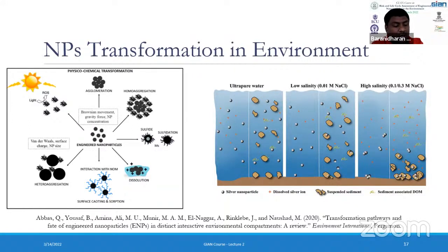So natural organic matter, which is present in natural streams of water, mainly surface water, refers to the heterogeneous pool of organic compounds, ranging from macromolecules, be it humic acid or fulvic acid, or otherwise extracellular polymeric substances, to low molecular weight substances such as carbon-based compounds and ligands, mainly chlorides or sulfates based amines, carboxylic compounds, OH compounds, and thiols, that is nothing but SH compounds, found in the natural aquatic environment.